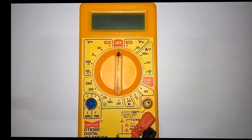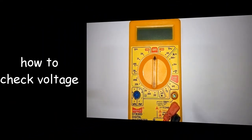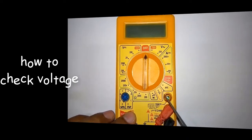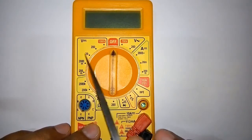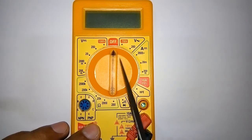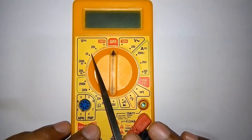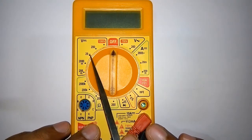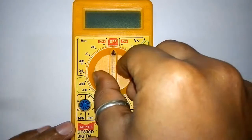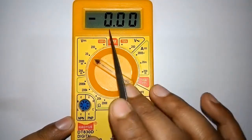Now I'm going to tell you how to check the voltage from your power supply. For this you will need a multimeter. There are different parameters you can check with this multimeter. AC, DC voltage, ratings are also given. I will put it to 20 volt DC.